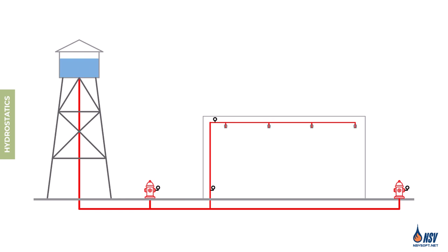In the diagram, we can see that the pressure gauge installed on the branch line is located closer in elevation to the water source compared to the other 3 gauges. Since static pressure depends on the elevation difference between the water source and the gauge, a smaller elevation difference results in lower pressure. Therefore, we can conclude that the gauge on the branch line will show a lower pressure reading than the others.